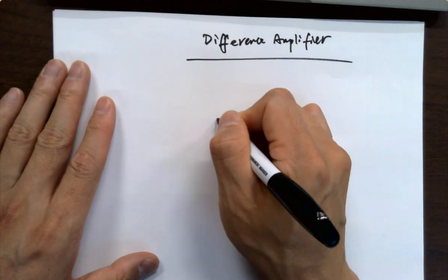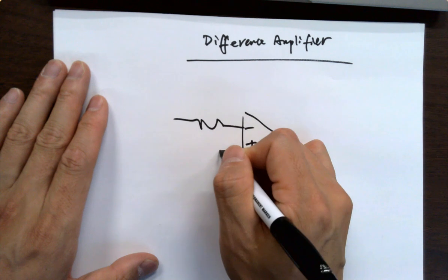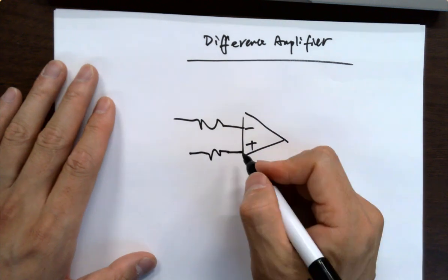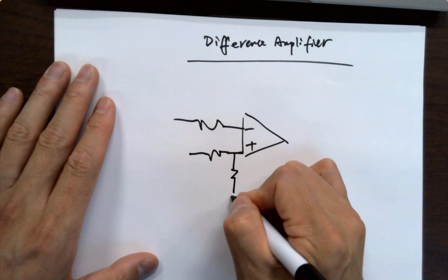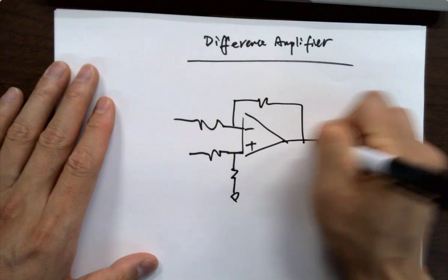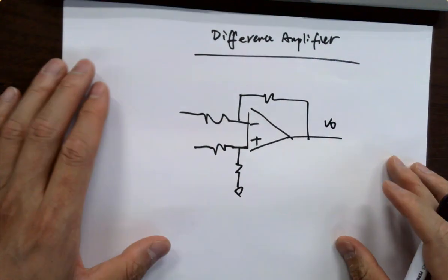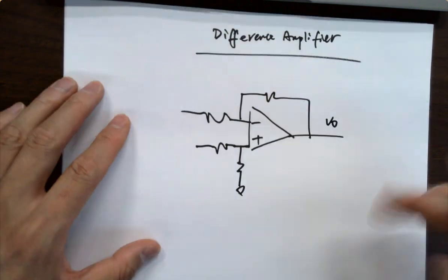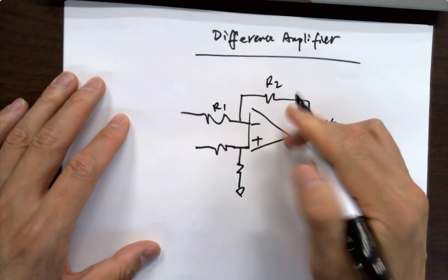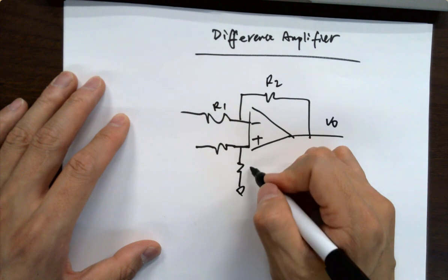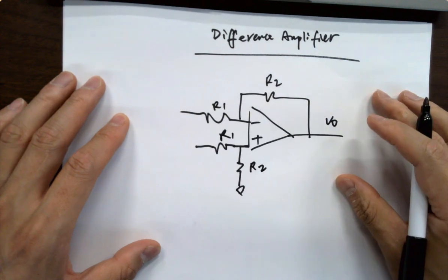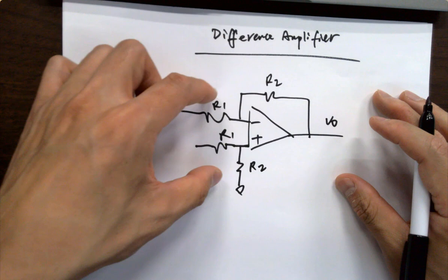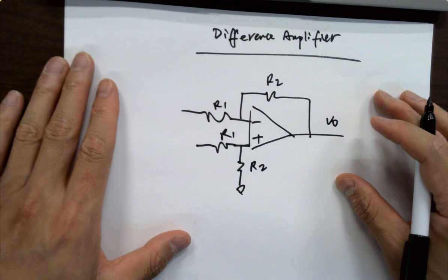What you need to know is this is a super practical configuration, and it's used in industry a lot. It looks slightly different, right? You have two resistors, R2 and R1, and they have the same values. It's symmetrical, so I'm labeling these as the same resistor. Keeping the same ratio will improve the quality of the amplification.